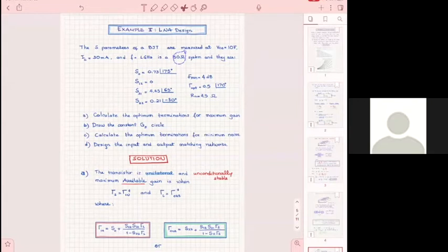So you cannot use the same scattering parameters, design the transistor at one frequency, say the frequency is 10 gigahertz, and then plot from 1 to 100. Who knows what crazy things you're going to find out in there.